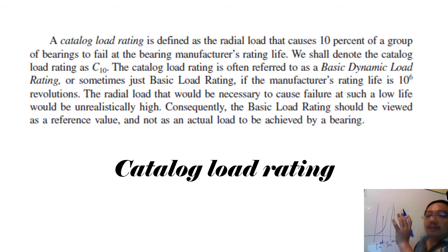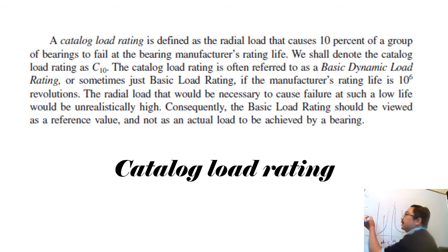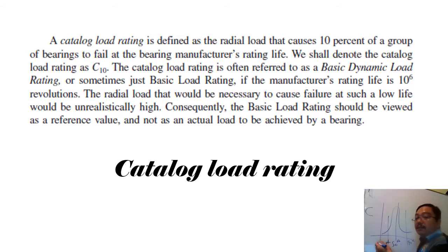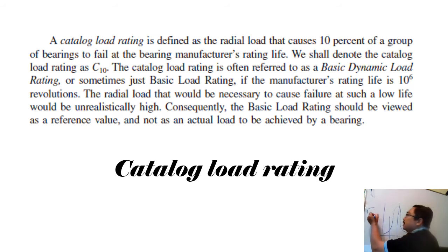The catalog rating is represented by the word C10. The unit for C is force. In other subjects C means constant, but not in this subject. In load rating, C refers to the force, the load of the bearing that you desire.